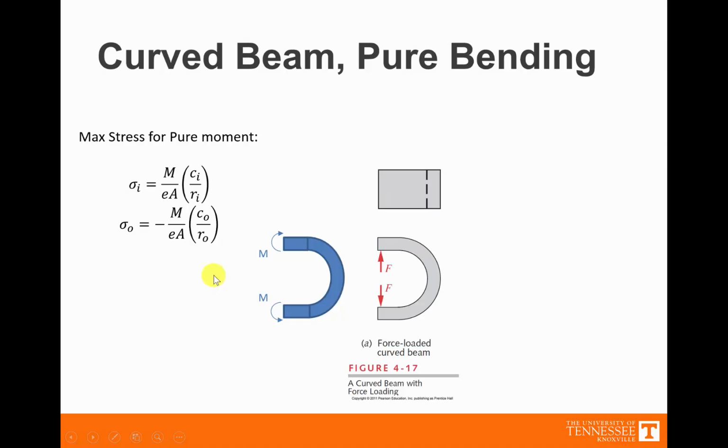There's a lot of cases where instead of a bending moment being applied, we can actually have two forces, for instance, a hook or something like that. So this is a fairly common analysis, and looking at this analysis, it's now become a combined loading. So we have a moment that's induced. If you were to do a free body diagram across the interior right here where this break occurs, you would recognize there has to be a moment that counteracts the moment that's created by this force times the distance away that this is. But there's also an axial load.